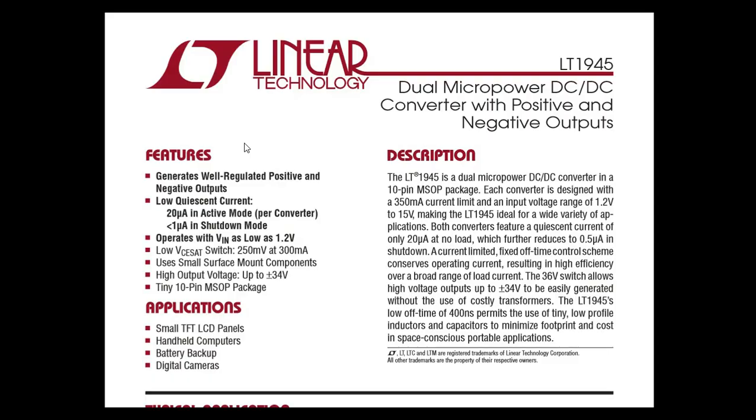If you look at the features, it generates well regulated positive and negative outputs with low quiescent current of 20 microampere, which is very low in active mode, and less than 1 microampere in the shutdown mode.